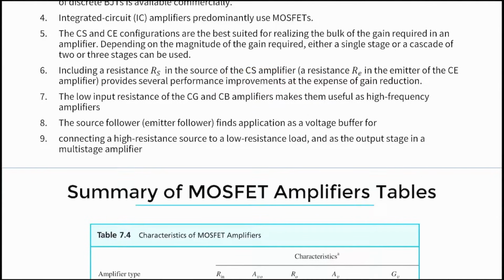For example, the input resistance also increases. The only thing is that the gain decreases, and the bandwidth for the operating range can handle higher frequencies, that's all. Most of the disadvantages, or what we lose, is the reduced gain, but as I said, the reduced gain isn't that big of a deal. We prioritize stability more. If the gain drops, what can we do? Just connect 2 stages and the gain will increase. It's not that difficult, right?